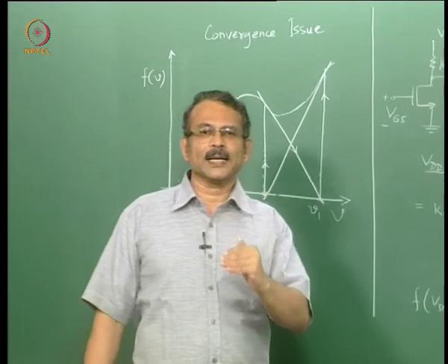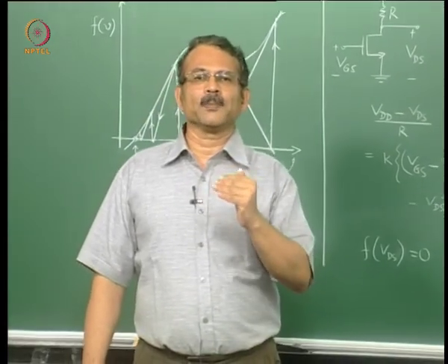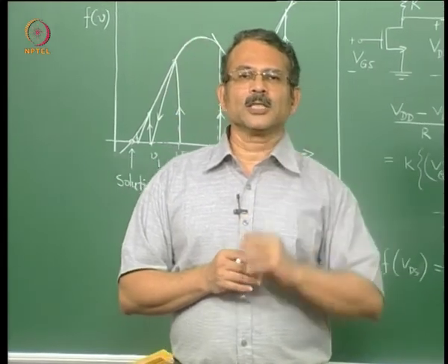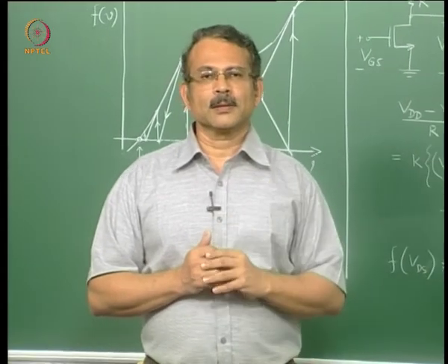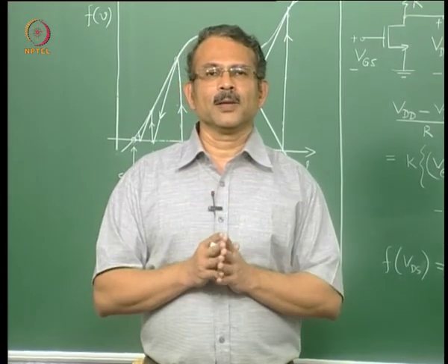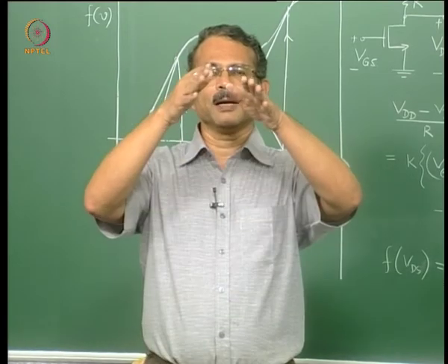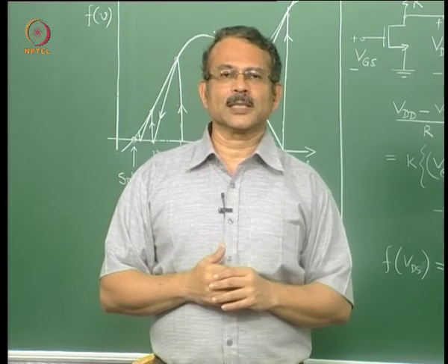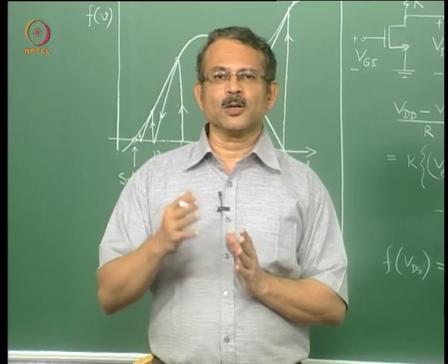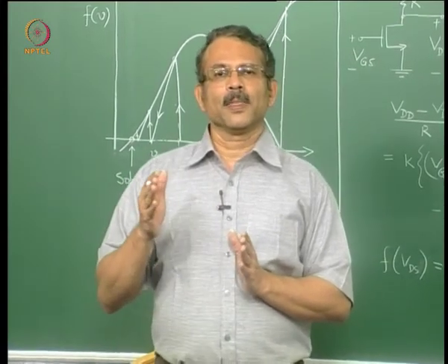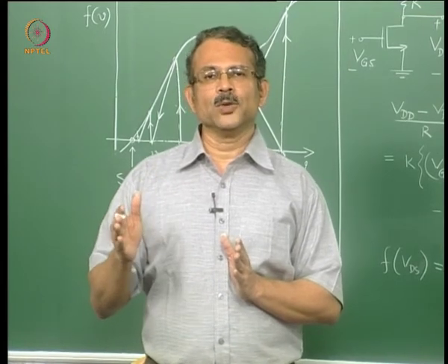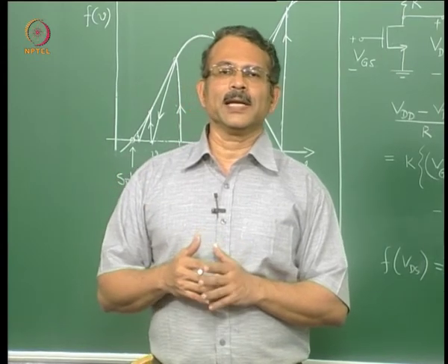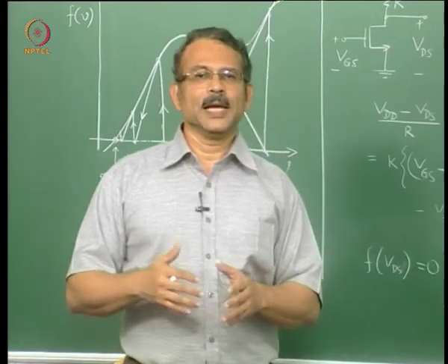So that is why asymptotic correctness is a very important criterion for compact models. When we talked about the physical basis, we did talk about asymptotic correctness. When we talked about the spreading resistance model, the very simple model without improvement, which was based on a constant angle spreading current, was not asymptotically correct. Please recall that discussion. And then we did make some changes in the model to bring about asymptotic correctness, that is the correct prediction of the right value of the quantity being modeled even for very very high values of the independent variable.